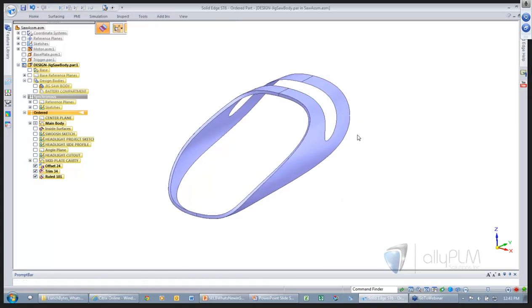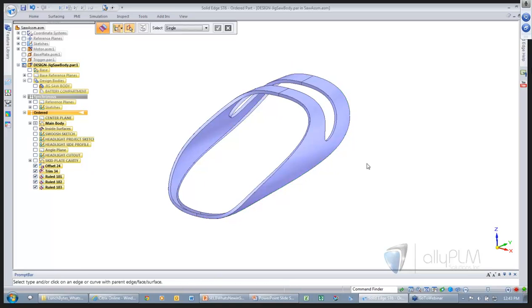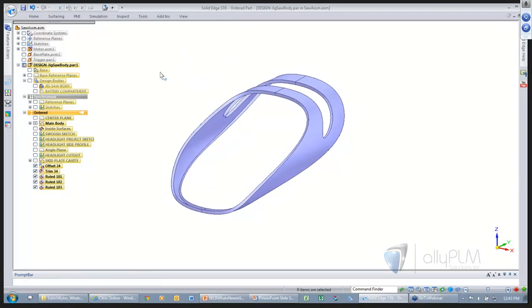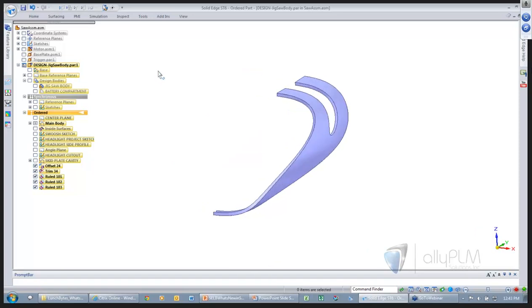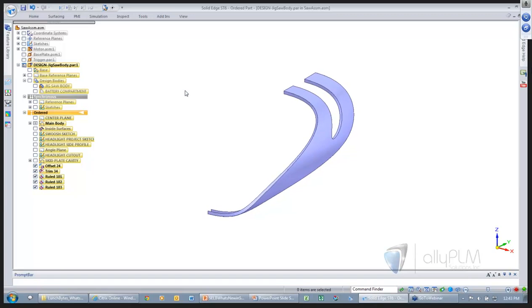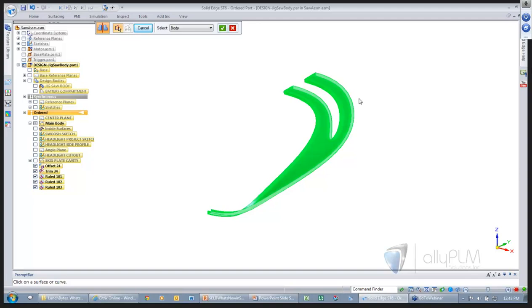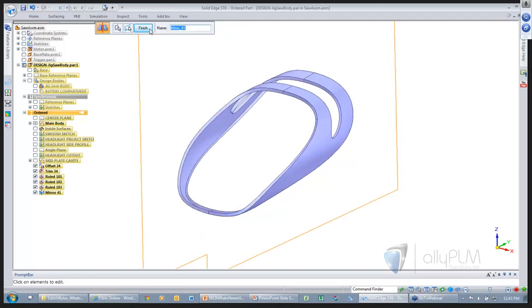I'm going to create some other ruled surfaces the same length back through there, and obviously I'm getting the reflective display to show what it'll look like once it's mirrored. I have a shortcut mapped, F4, to turn the reflective display on and off, so we're back to the actual geometry, and I'm going to mirror those sheet bodies, surfaces, about my center plane to get the full shape.